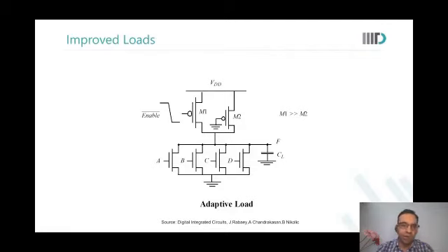So in a synchronous system, when the clock comes, that is when most of the gates toggle. That is when most of the inputs will toggle, because the flip-flop will give outputs only at that time. Otherwise, flip-flops will also have their outputs stable, is it not? Yes, sir. So you can say after the clock comes, I will have a 20 or 200 picosecond enable pulse, so that all the combinational gates in my system would evaluate.